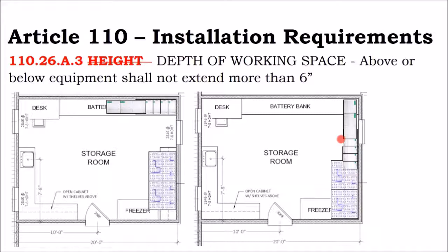And so you can't have one piece of equipment that sticks far out from the wall and another piece of equipment that's kind of inset into the wall stacked on top of each other. Those technically would be different zones. It would violate, you would need two different working spaces. So to put them on top of each other, you'd have to have a 6.5-foot section and then another 6.5-foot section, although that would be very impractical for the most part.